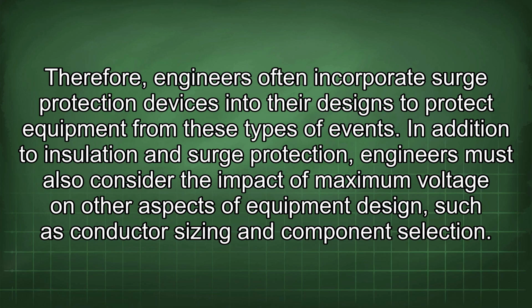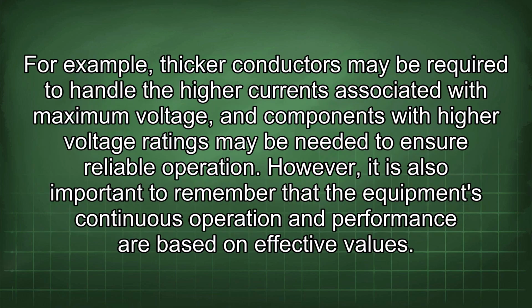In addition to insulation and surge protection, engineers must also consider the impact of maximum voltage on other aspects of equipment design, such as conductor sizing and component selection. For example, thicker conductors may be required to handle the higher currents associated with maximum voltage, and components with higher voltage ratings may be needed to ensure reliable operation. However, it is also important to remember that the equipment's continuous operation and performance are based on effective values.